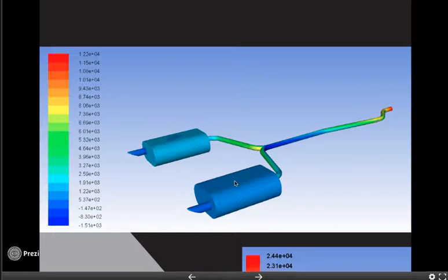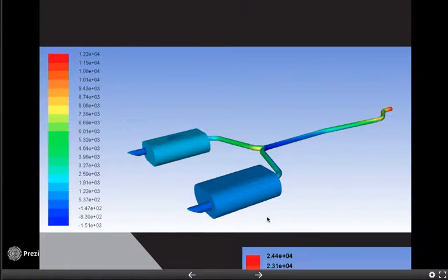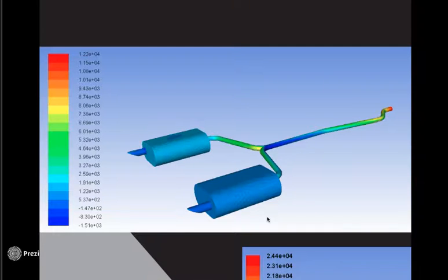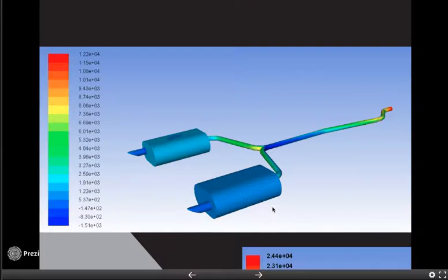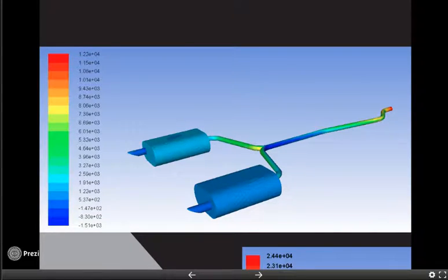And in this one, you'll see the difference. So here we see that the max here is 122, which, as you can see below, is about twice the pressure from the single exhaust, which is going to result in higher temperatures and just a whole variety of different issues.